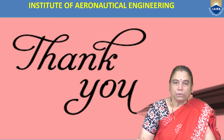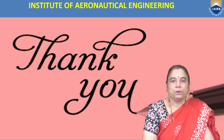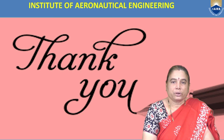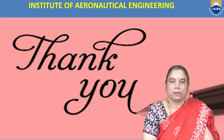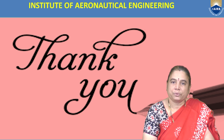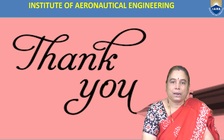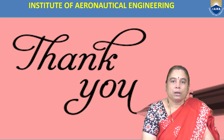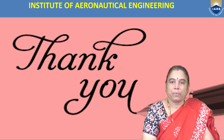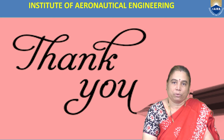8086. So in this video, we have discussed what the instruction set architecture is, where it is placed, how it acts as an interface between the software abstraction layer and the hardware abstraction layer, and what the varieties of instruction set architectures available are, and by considering two popular architectures, RISC and CISC, explaining their features and comparing and contrasting the RISC and CISC architectures.